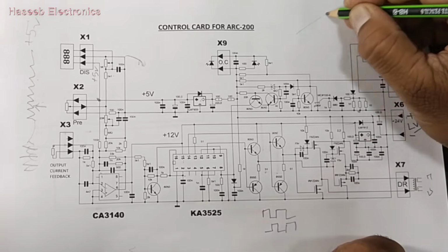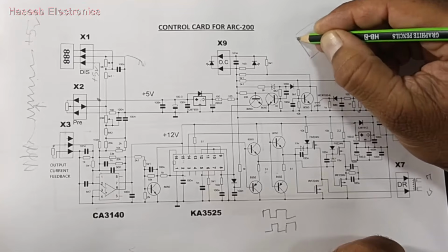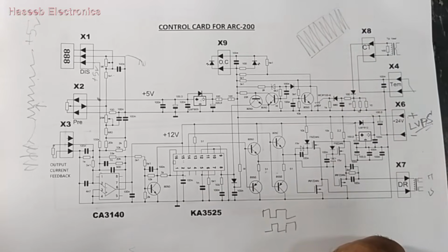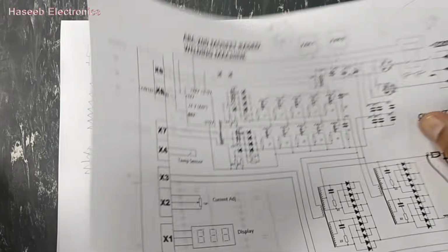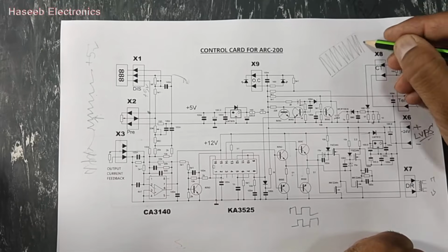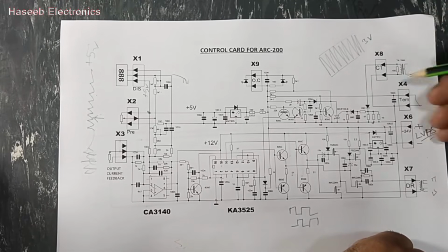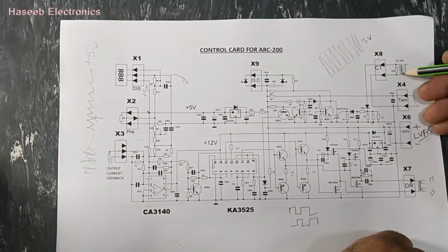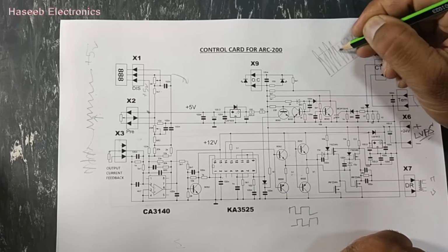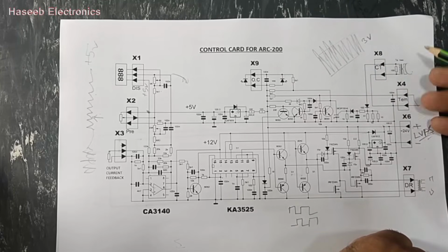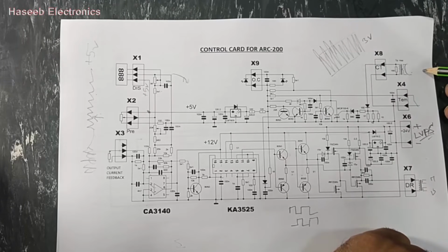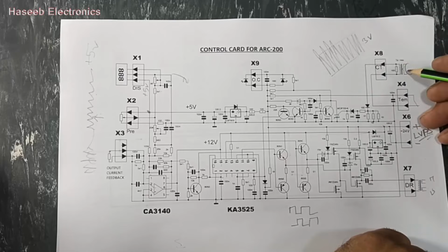For example, this circuit is allowed to work with 3 volt. We can say, as per this ratio, for this example, 30 ampere is 3 volt. If the current increases in this section, it will increase the amount of voltage. For example, we receive 4 volt pulses. That means the current exceeded the allowed limit. Allowed limit is 30 ampere and we are taking 4 volt.